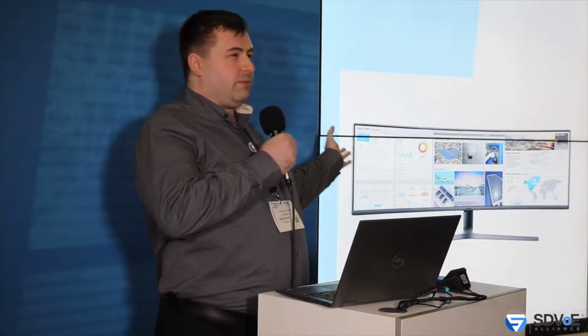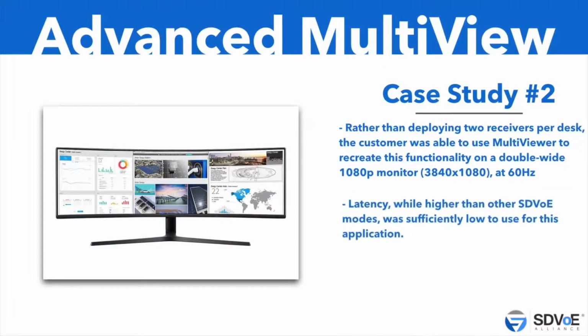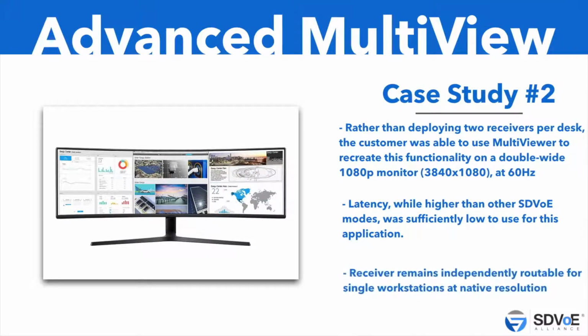This gave them quite a bit of flexibility because they could also route that 3840 by 1080 monitor as a single monitor to any computer in the system. The multi-viewer was able to support any type of source sent to that second virtual monitor on the double-wide display. The latency is a little bit higher than the other modes of SDVoE, but it was still sufficiently low for the type of KVM usage they had. And again, the receiver was independently routable for a single workstation with a double wide, with native gen-locked support and the 100 microsecond latency that SDVoE is so famous for.